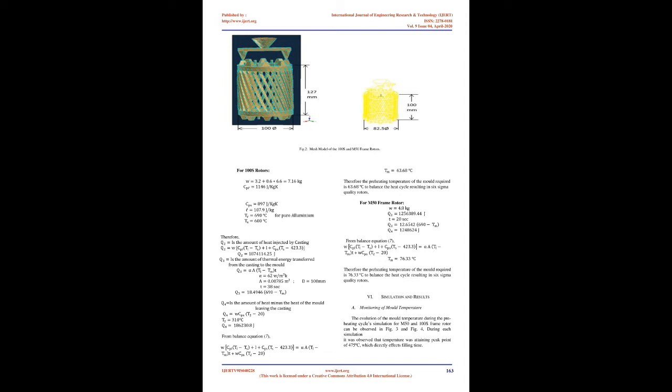Pressure die casting essentially consists of the following parameters: pouring molten temperature, preheat temperature, filling time, riser design, plunger velocity, die holding time, injection pressure, die coat material, solidification time, die coat thickness, and cooling system. Fig 1: cause and effect diagram for casting defects.